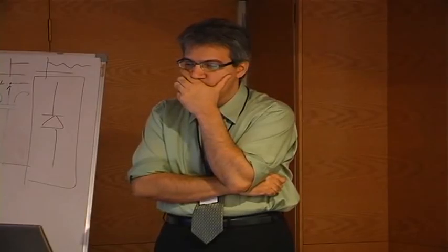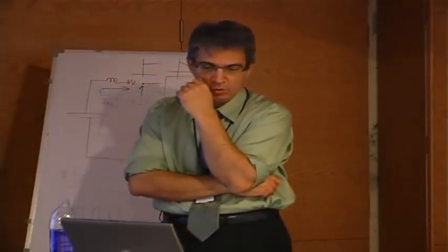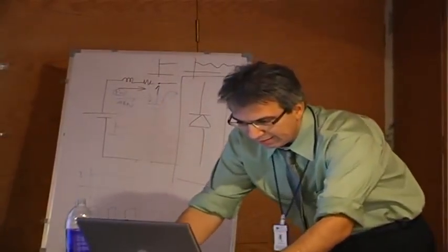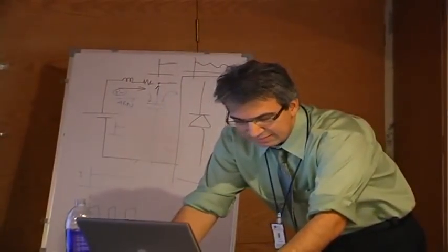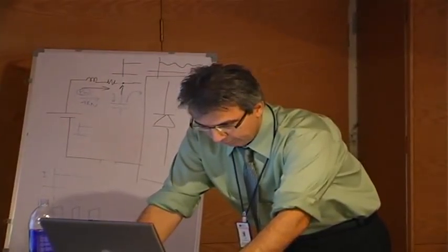Okay, let's look at our results. Just one question about this waveform. Are these spikes real, or are they actually observed in machines, or are they just simulation artifacts? So this one, I think, could be related to reverse recovery of some of the diodes. I'm not sure. We can check. Plot the diode current. Pardon me? Plot the diode current. Yeah, we could plot the diode current.